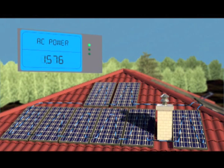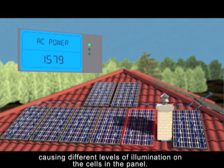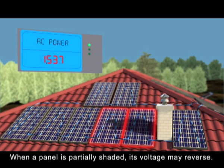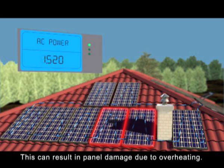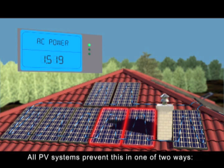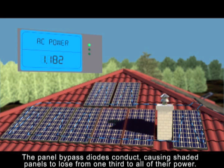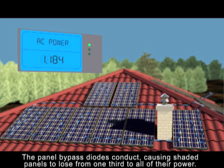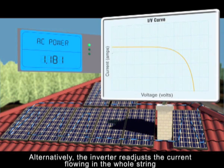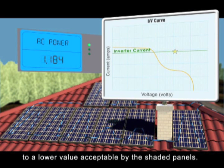The power loss from partial shading occurs when part of a panel is shaded, causing different levels of illumination on the cells in the panel. When a panel is partially shaded, its voltage may reverse. This can result in panel damage due to overheating. All PV systems prevent this in one of two ways. The panel bypass diodes conduct, causing shaded panels to lose from 1/3 to all their power. Alternatively, the inverter readjusts the current flowing in the whole string to a lower value acceptable by shaded panels.